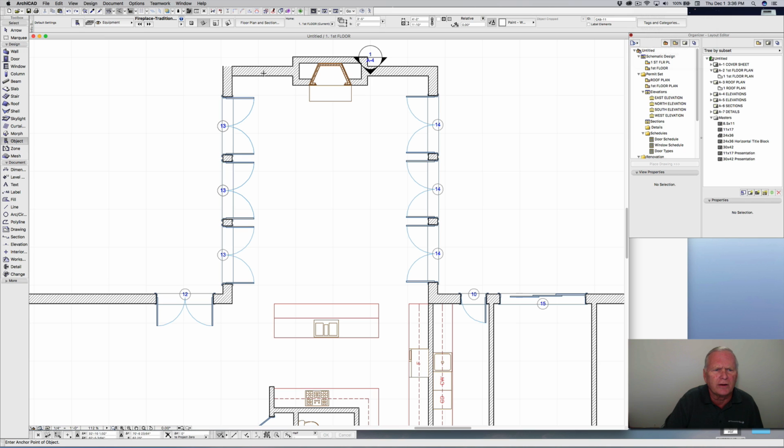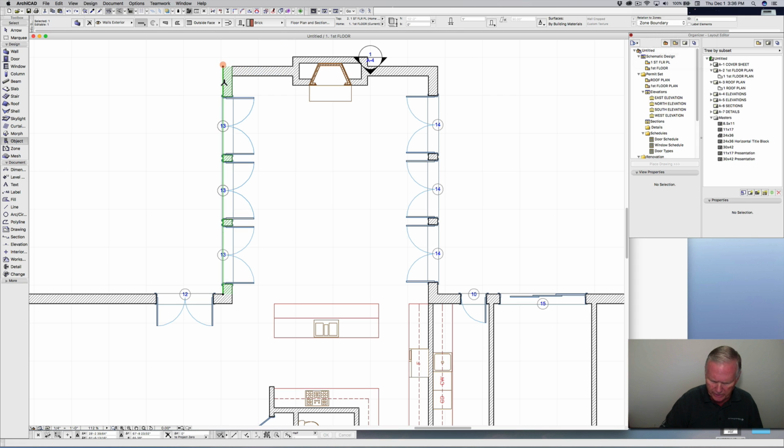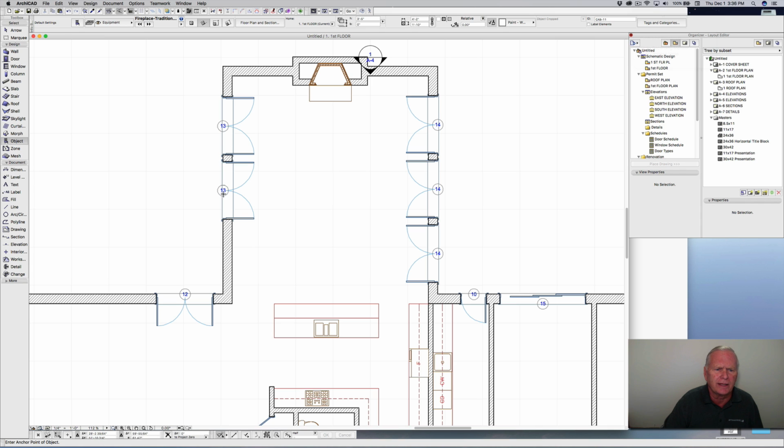Right, I figured out what was going on here. We actually have two walls here, one with doors in it and one without doors in it. And so we're going to click on that one and hit delete. And that obviously had a wall with a door in it. You see how it now cleaned up, that door went away. And I think that's back when we clicked on that wall and door and I had to unclick that, we somehow got that problem.